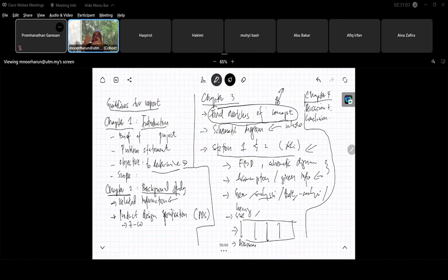So before you do the calculation, once you have the proposed dimension, then you do your calculation. So your final CAD model will sometimes change after you do your analysis. After you do analysis, for example fatigue or static failure analysis, you do your critical analysis on your parts.